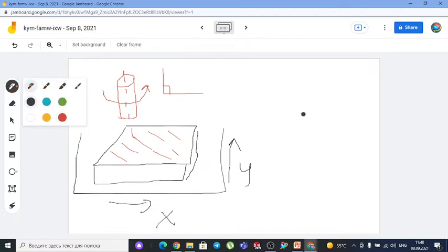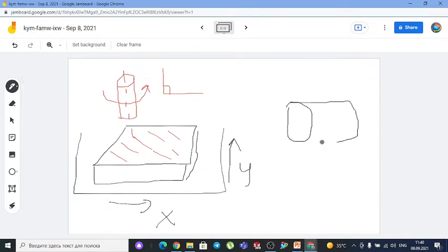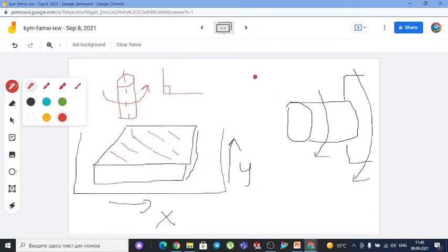In the case of the turning operation, we will work only with cylindrical elements. The cylindrical element is fixed on the spindle. The spindle rotates around its axis, and since the spindle rotates, the workpiece also rotates. Then we have a single point tool. Since the workpiece rotates, the single point tool removes material layer by layer from the surface of the cylindrical element in order to obtain the final shape.